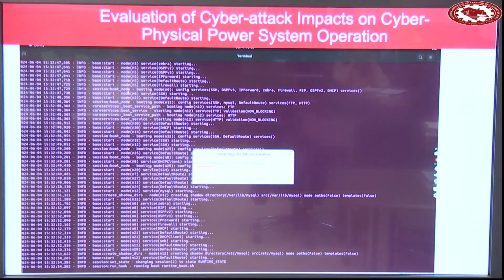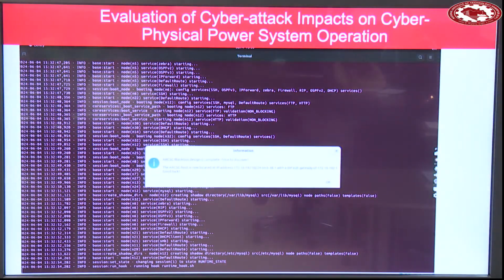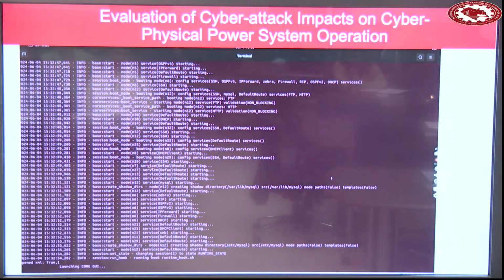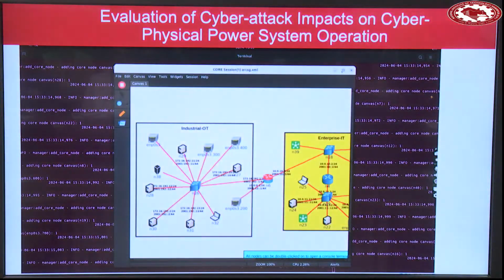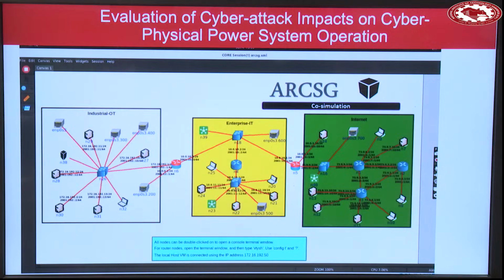So we are initializing a number of nodes as communication nodes. We're describing how many devices we have and what power system model we are using. Power systems have different models depending on how large a system you want to test. They have a small test-scale system, and then larger ones, which we call IEEE bus systems. That's how it looks. Once you are able to run it, you create a number of nodes, connect the system all together, and then you can inject data at any point in the communication network, then run the whole loop and test it.